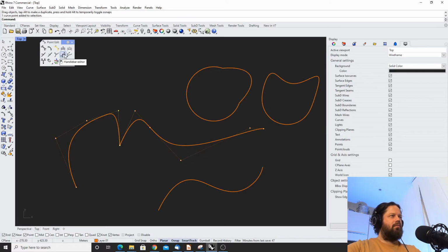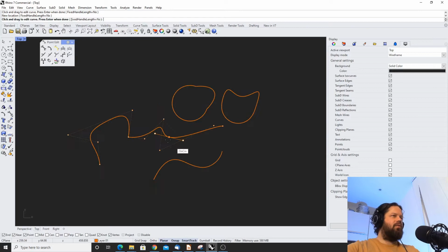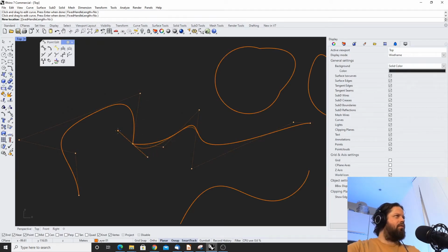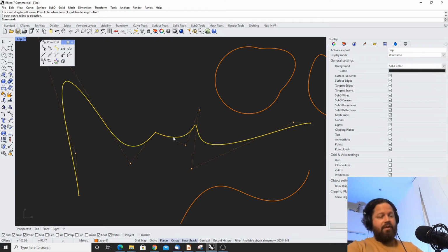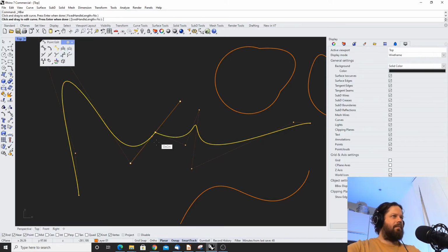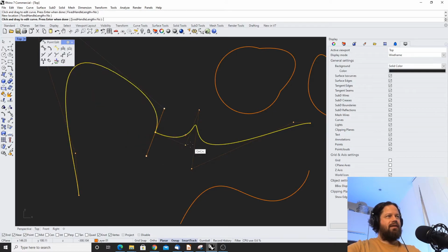I can then also go even a bit deeper and control the direction of the curves going from these points. So the handlebar editor is this. If I now click here, select the curve or surface to adjust, okay. And now I can adjust that kink actually to only one direction. It's as if there are 2 directions. So it's adding really the maximum control over these curves. Don't know if I can control here the other one, the other side. It seems like it has this direction. What if I use the flip command? So if I use flip command, then it would be interesting now if it's adjusting the other side. Yes, that's interesting. So basically a kink has a direction, and the other side of the kink I can adjust here with the next control point. That's interesting. I didn't know.